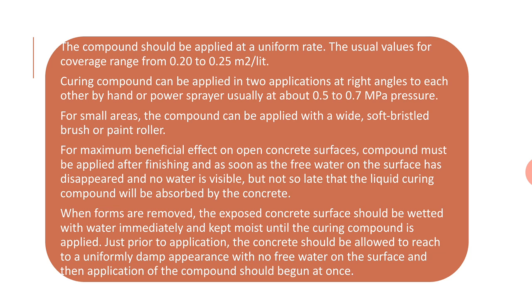For maximum beneficial effect on open concrete surface, compound must be applied after finishing and as soon as the free water on the surface has disappeared and no water is visible, but not so late that the liquid curing compound will be absorbed by the concrete.